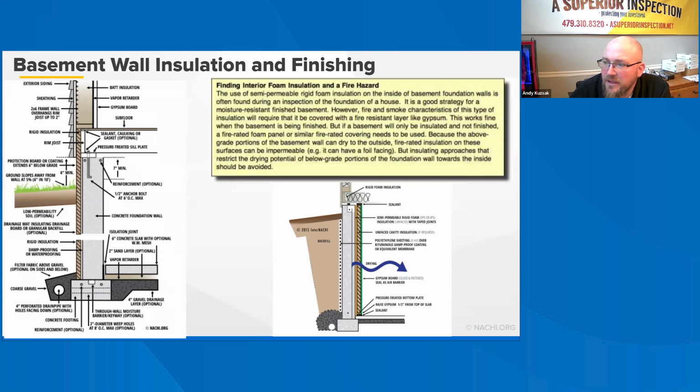which is this right side here. To prevent humid basement air from leaking into the finished wall assembly and condensing, the interior side should be sealed against air leakage. The ideal approach uses gypsum wallboard as an air barrier, requiring sealing any panel penetrations or leaks. Air sealing basement ceiling penetration should also be addressed. Additionally, joints in the foam insulation should be taped and sealed.